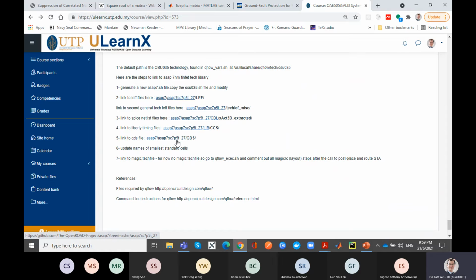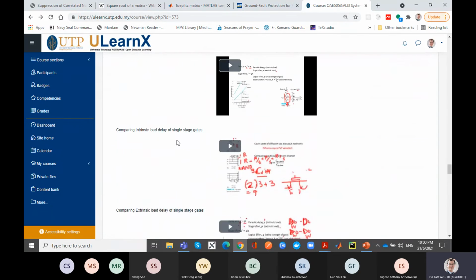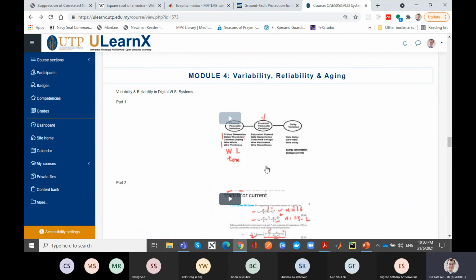And then if you look at the static timing analysis and look at more nodes, you can even do a distribution of the timing for all your nodes. Like how far apart is your critical path from your near critical path, and how far apart is your near critical path from the average number in your circuit. Because, as you will see in the lectures on variability and reliability, which you should be touching now, nowadays it's not just the critical path you have to worry about. You have to worry about the near critical paths, the paths that are not really critical, but because of process variation, they can end up being a critical path when you fabricate the chip. So try not to worry too much about that.